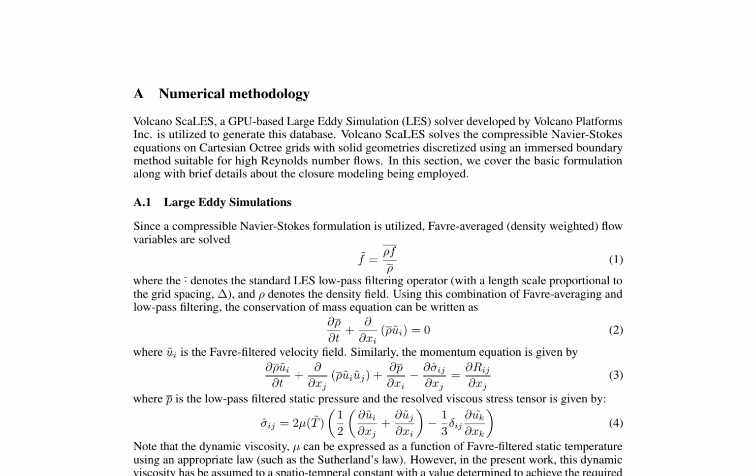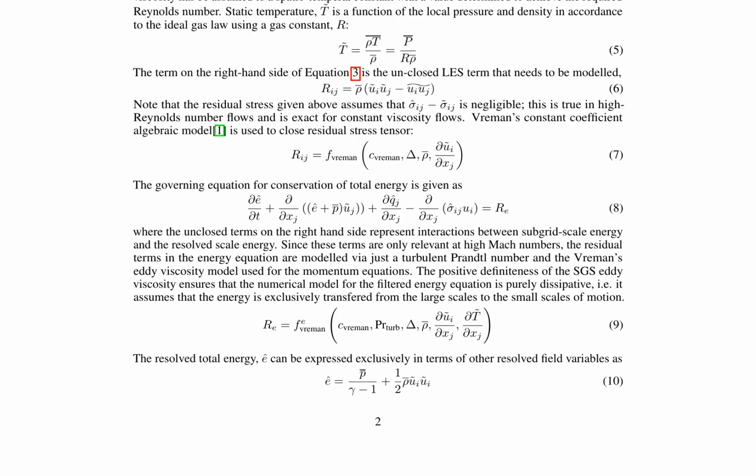The momentum equation incorporates the low-pass filtered static pressure and the resolved viscous stress tensor, highlighting the crucial role of dynamic viscosity, assumed to be a spatiotemporal constant. The energy equation is also formulated, focusing on the interactions between subgrid scale energy and resolved scale energy.